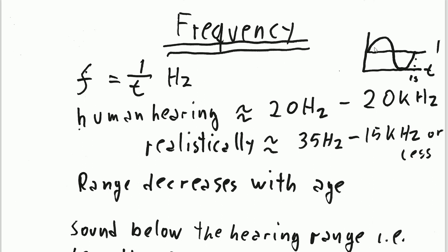Frequency, the definition of frequency is that there's a change occurring. So we've got a change here on this waveform. That's my 0 volt line here, or my zero line right in the middle. And then it goes up, and then it goes down and back to 0. And then it reverses on itself and it goes the opposite direction, goes down and goes back up again until it hits the 0 line again. And it repeats itself. So going all the way up and going all the way down and then back up again, that's considered to be one cycle. And what we measure is how many cycles, or how many repetitions of this cycle, we have in 1 second. And that is the definition for frequency.